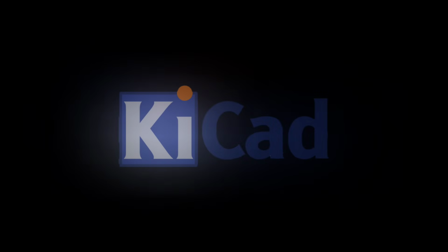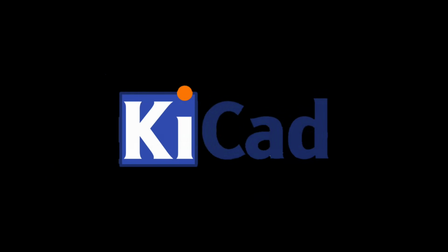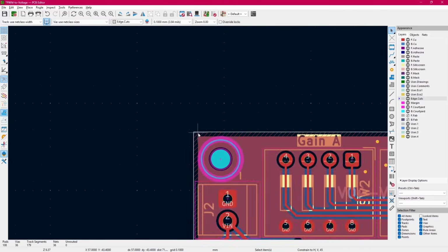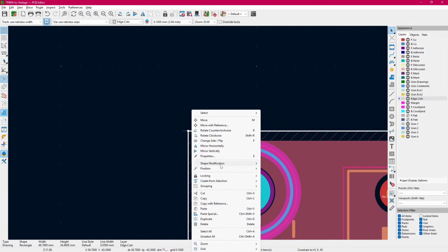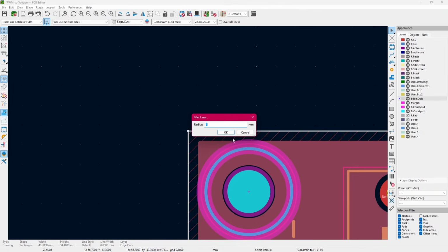Hi, in this video I just want to show you some KiCad tips and tricks. Let's get into it. Let's say you want to round this corner here. Well, just right click on it, select shape modification, fillet lines, and then you choose the radius you want.